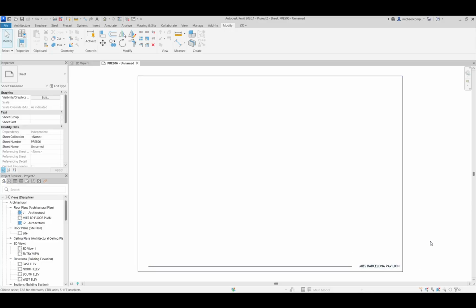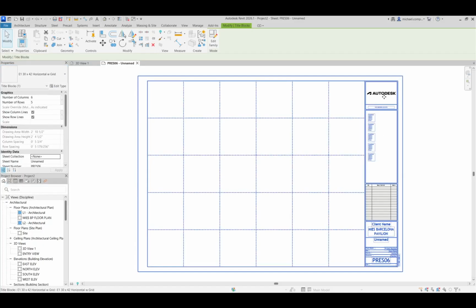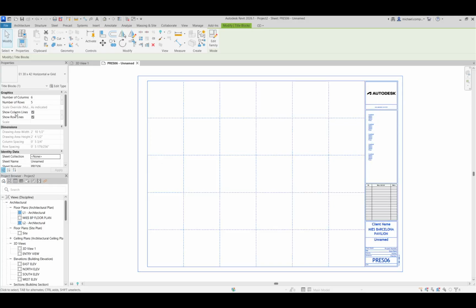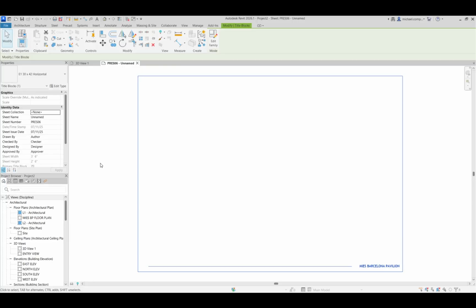So there we go. This is a presentation sheet. Again, if you wanted a construction documentation sheet, there's a bunch of those that come with Revit. You can edit the Autodesk to put in your own logo and all that stuff. But for what we're doing, which is presentation drawings, this is what I wanted. Okay, now how do you populate? There's, again, 500 ways of doing any one thing. I'm going to show you my preferred method.